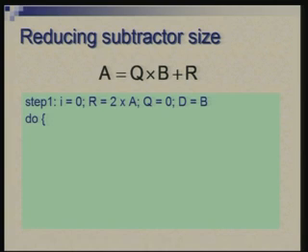Okay. So, you recall that the first time we shifted D was by n minus 1 bits and not n bits. Okay. So, the same position is maintained here, because D will now be subtracted from R in its left n positions, okay, as you will see now.